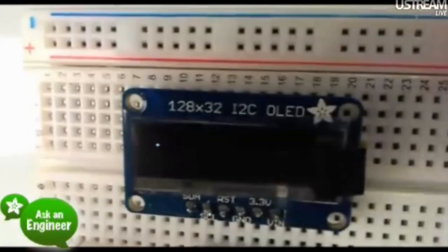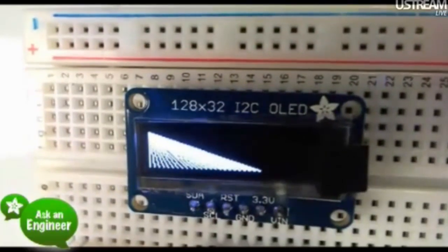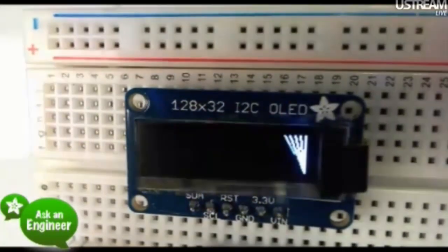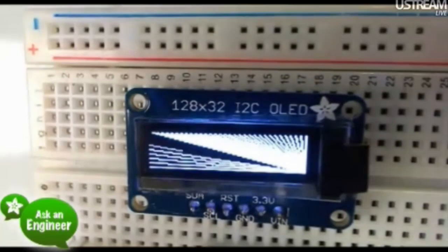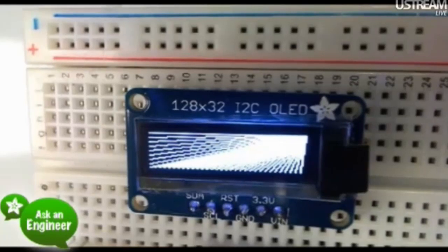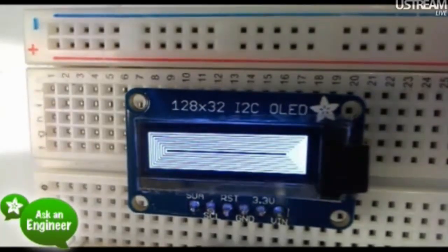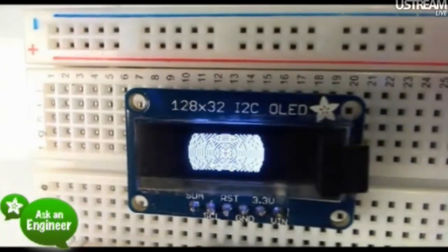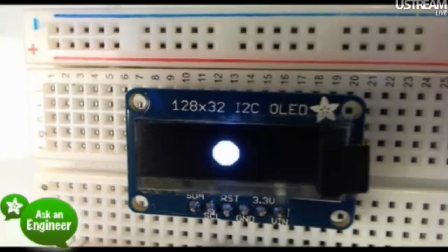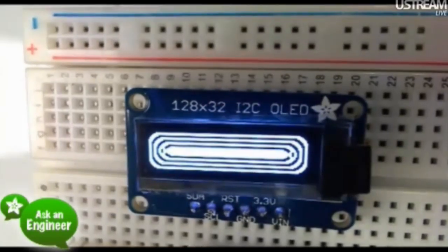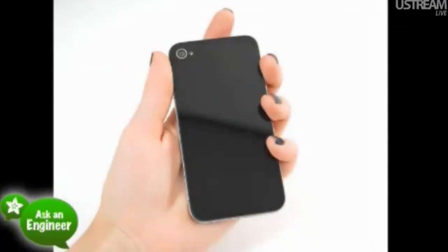We have an SPI version, and this is the new I2C version. You only need 2 pins to talk to it. It's a little bit slower than the SPI, but our code does great. It's the same size and shape basically as the SPI one. We just wanted to have 2 options, because one does SPI, one does I2C. If you have a chip that you don't want to use the SPI bus for, but you have I2C, it's really easy. It works great. Super bright, lower power, and very easy to use.